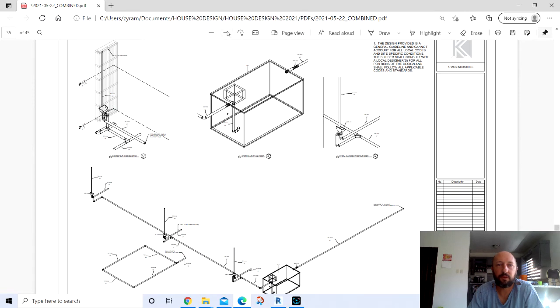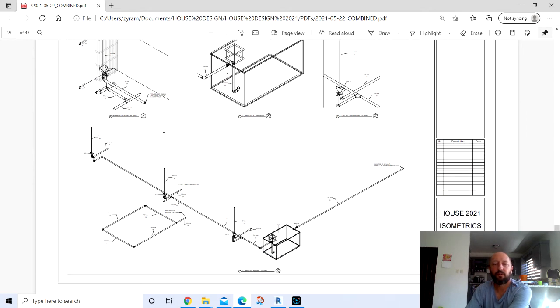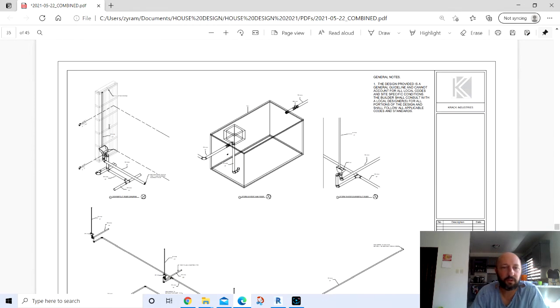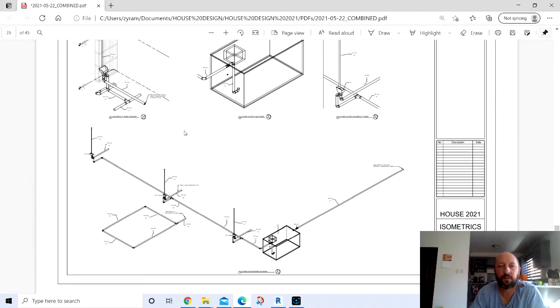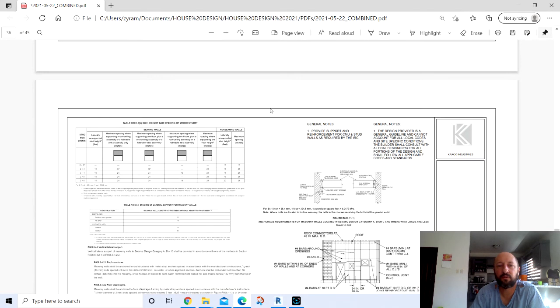And we have a few details of your downspout diverter. Your downspout diverter will want to have a small hole drilled in it, a weep hole, so that it empties slowly. You just want to get the first flush off your roof into that diverter so that all the leaves and everything don't go down into your cistern.